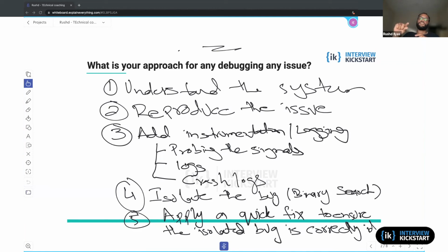Using that, you can find the map file for that firmware image, and then see which function it was in when it asserted or crashed. So these are some of the ways you can add crash logging or assertions and then use them.